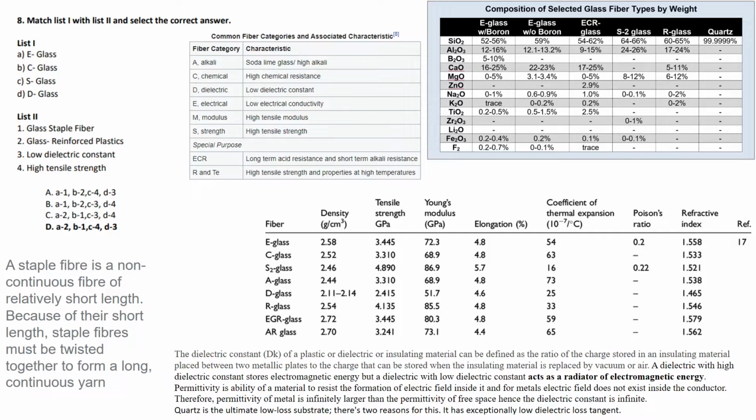As this chemically resistant glass fiber composite would only be used to store materials within itself which are chemically more corrosive. So for this, you don't actually need strength. That is, you'll not be storing highly compressed gases or something into this particular composite. You'll only be storing chemically corrosive gases or liquids within this glass fiber composite. And therefore, C glass can be staple fibers, and thus this entire column can be used as follows.